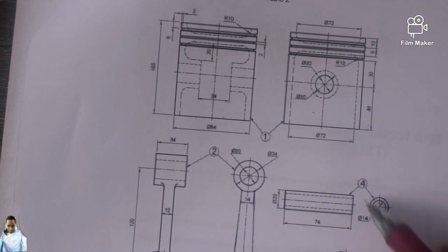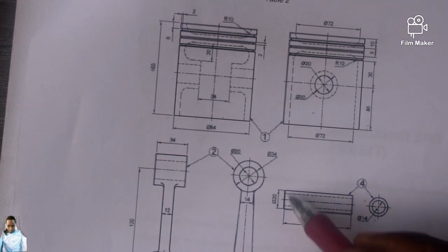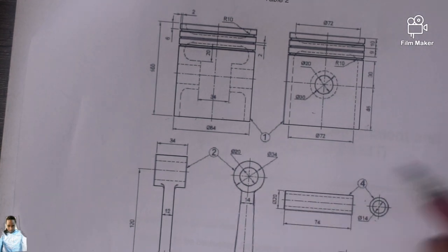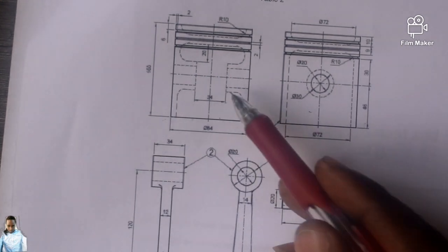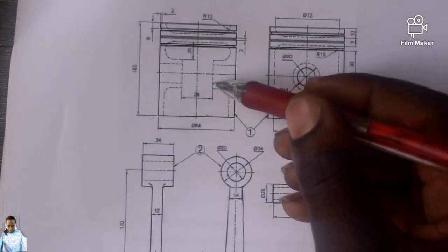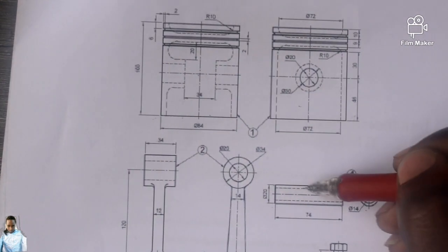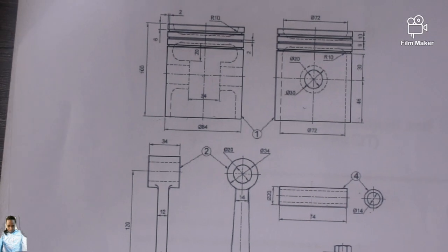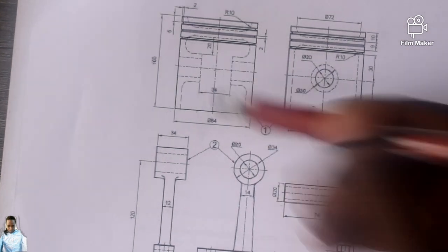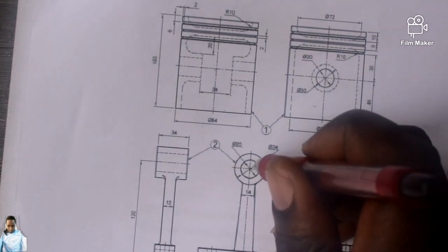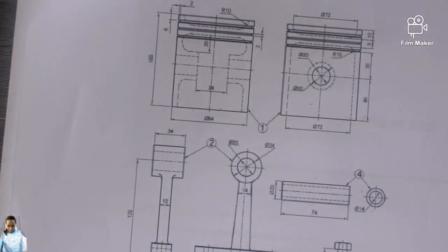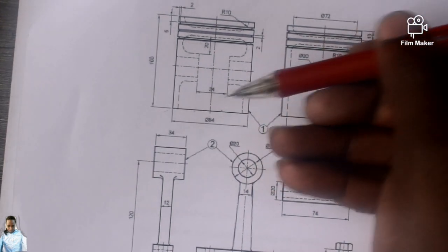So the outside diameter of item 4 is 20, so which means this 20 can be fitted there, you understand? And the shape as well, this is diameter, can be fitted there. So now the moment we put this item 4 there, we are going to work according to the center, so indeed item 4 can be fitted there. So you take item 4, you fit it in item 2, then you fit it in item 1, the 2 of them being fitted in item 1.